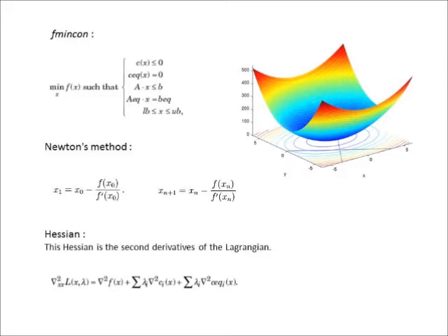The first solver we experimented with was the interior point algorithm, which is the recommended Matlab default solver. It assumes that the optimization function is convex. The solver takes the derivative of the objective function to determine the search direction using Newton's method. However, we do not know if the function is exactly convex in this case, so the risk of ending up in a local minima is very likely. The second one is the sequential quadratic programming, SQP, which requires the objective function to be twice differentiable and is more often used for quadratic functions and updates it at every iteration.